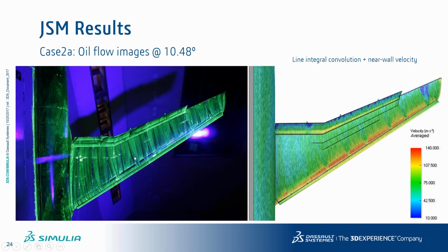In this case we can also look at a better insight into the flow field, like these visualization techniques they have in the wind tunnel that allow, for example, to see oil path lines. So you can see pretty much the areas of separation and the different flow patterns you've got on your wing. It's very interesting. It gives an extremely good insight into the flow and permits us not only to see if you're predicting the correct drag and lift, but also if you can predict the correct flow mechanism, which is most important, I think.